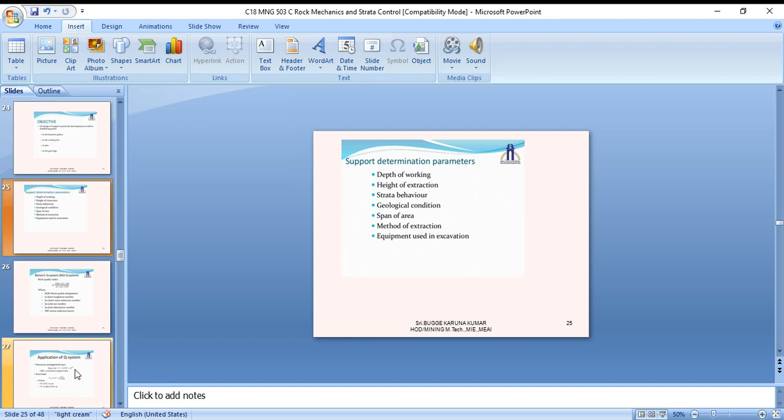In one group of these methods, the theory of elasticity is applied to identify the stress conditions prevailing in the rock in the original undisturbed condition, and then the distribution of stress and strain introduced by the excavation is derived. The concept of stress functions, though solvable under ideal conditions, makes the computation quite tedious, involving the evaluation of a number of constants.